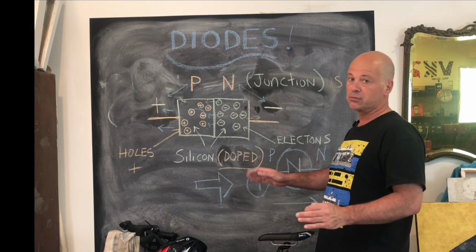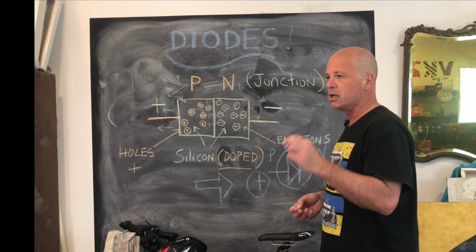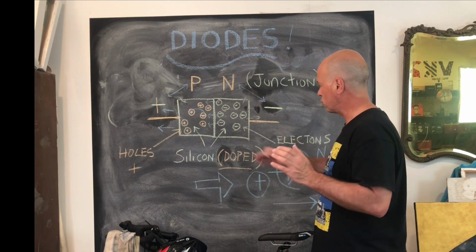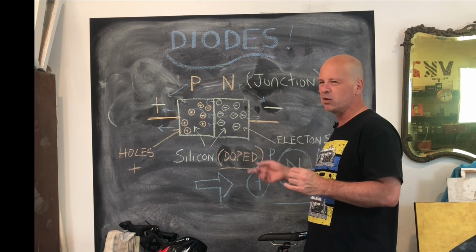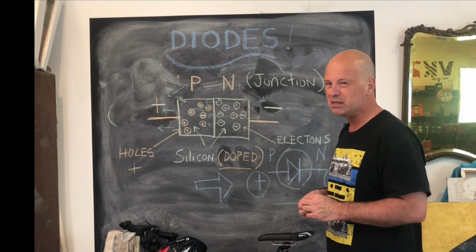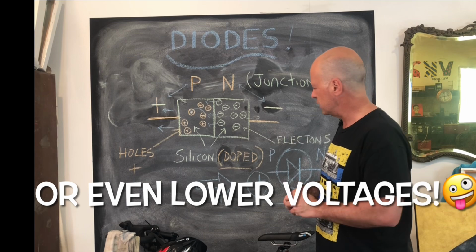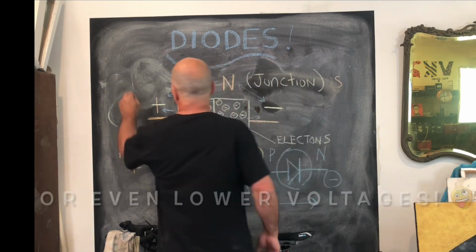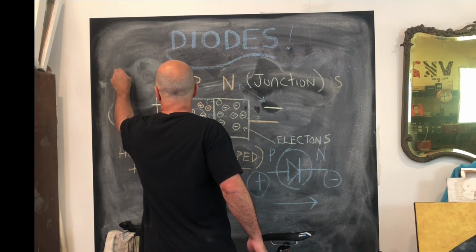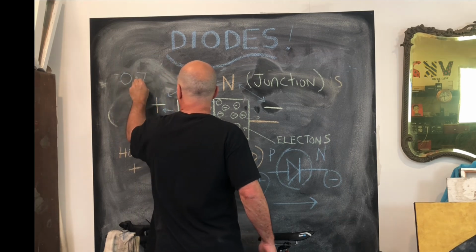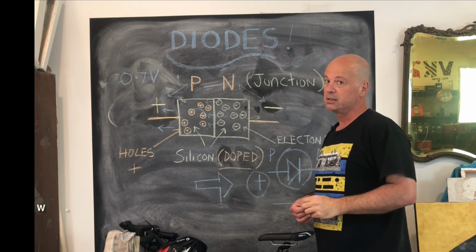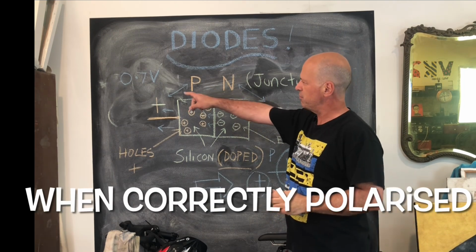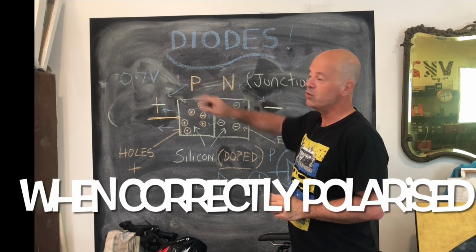And the bias voltage for a diode is what you need to have across it to get it to start to conduct. So unlike a piece of wire, which might start conducting at millivolts, for a silicon diode to be forward biased, you need 0.7 volts to get it to start to conduct. So that voltage is often looked for if you're doing fault finding.